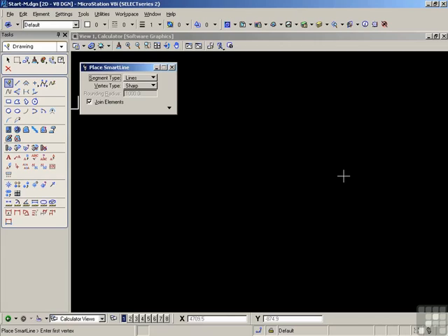With Focus in AccuDraw, F11, press the G key on the keyboard. That pops up a list of the AccuDraw shortcuts, and you can scroll through that list quite easily and see the shortcut that you need. Another way is to press the question mark on your keyboard, so Shift and question mark.